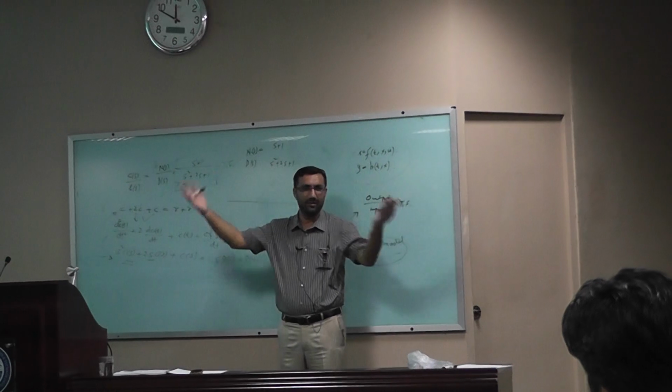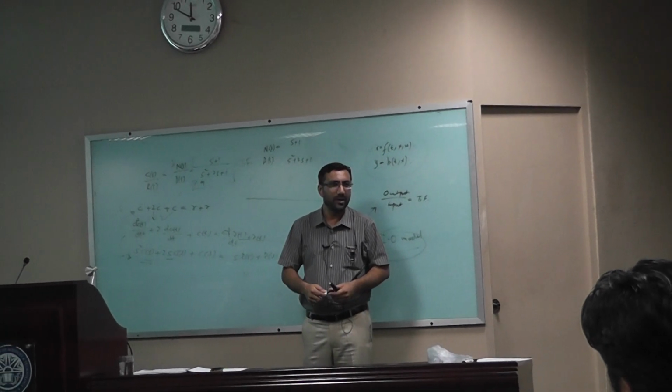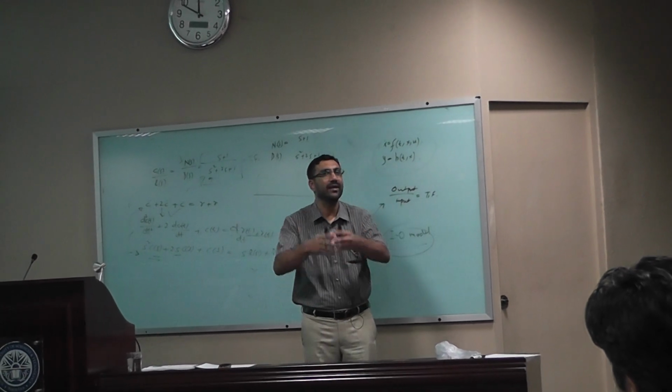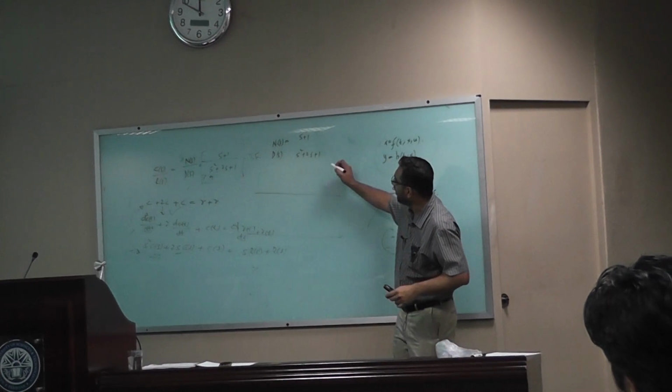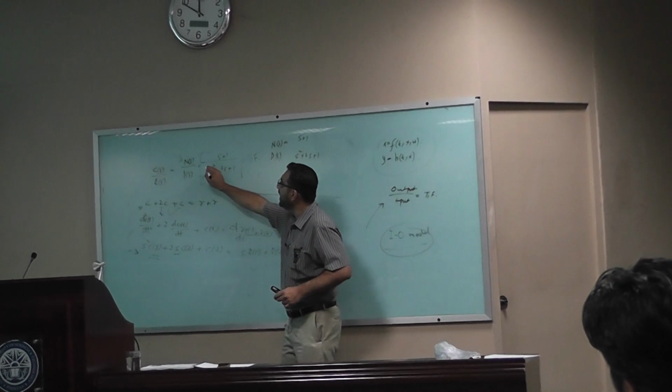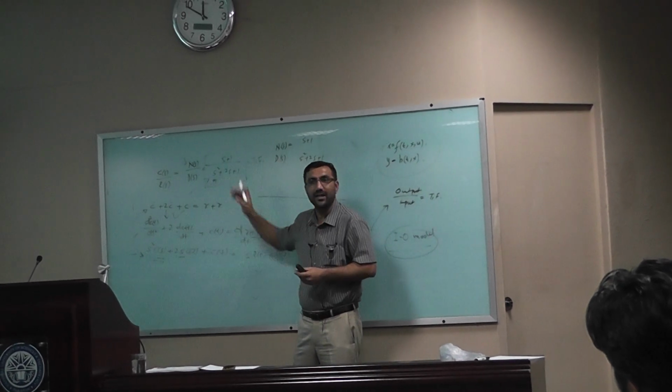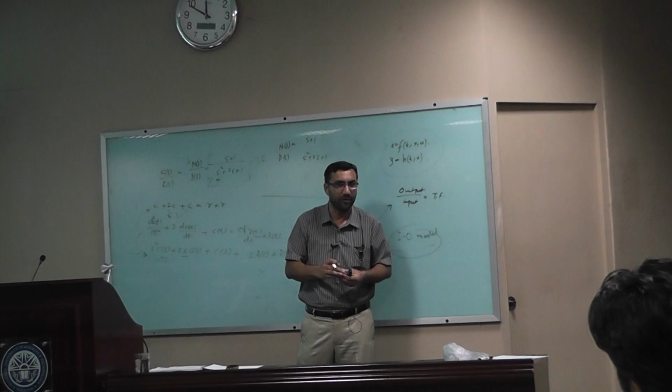Unfortunately, if you make a transfer function, you have to lose information because you are now banking on it in a linear system. Transfer function is a linear phenomenon. Why? Because it has to relate input and output in this certain way, which is given by this particular Laplace transform.